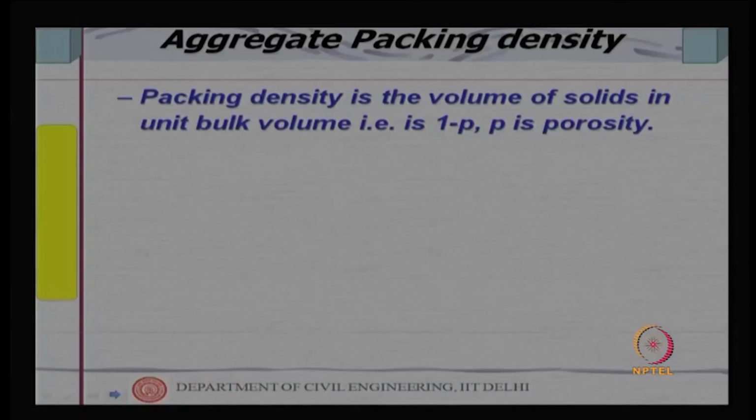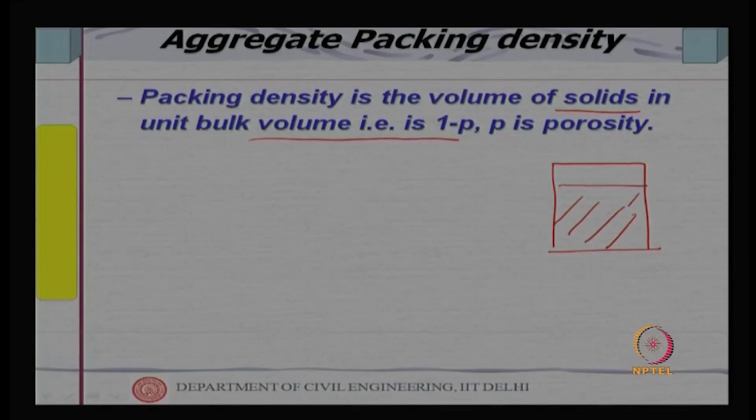Now, packing density we define as the volume of solids in unit bulk volume. So, if I have total volume V and volume of solids let us say is V s, and this is volume of pores, then packing density will be V s divided by V, where total V is equal to V s plus V p.